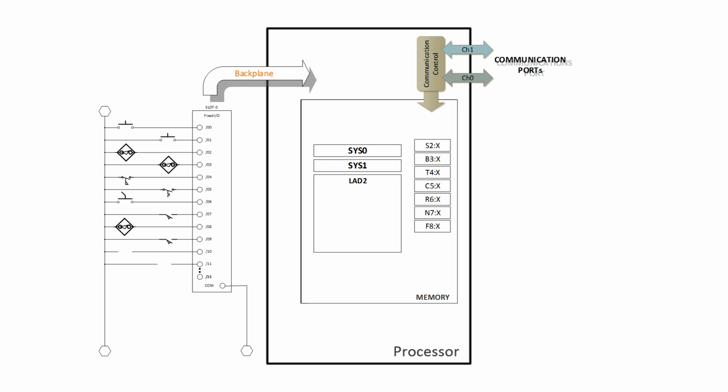Now, a backplane, and they are rapidly disappearing. ControlLogix still has a solid rack or chassis with a backplane. But in a nutshell, the backplane, and we'll simplify it down to 16 conductors, kind of like a ribbon cable, but traces on a circuit board that run the full length of a chassis that can accept multiple modules slid in and plugged into those 16 common conductors.